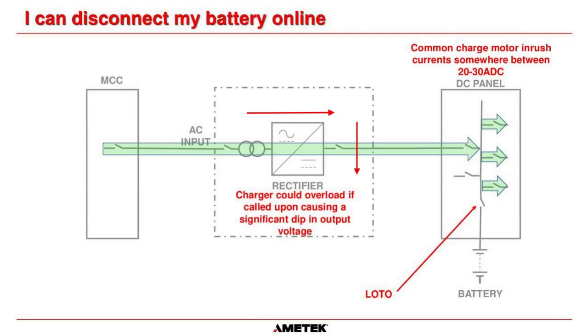So it is absolutely incorrect to say that you can disconnect a battery to do work on it, leave your charger online, and everything will be okay. That is not the case. It is such a common misconception.